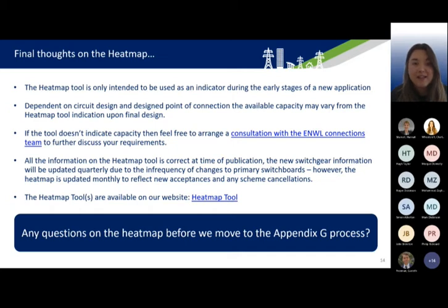That's because at the end of the day, it is just an Excel spreadsheet. So there are lots of different permutations of the network that we can't capture in those calculations. So there can be issues with things like voltage step or voltage swing, particularly for batteries, that we'll only see out of doing network modelling, which we do when we get formal applications. So as I say, a handy tool to have, but it won't give you a guaranteed point of connection moving forward.